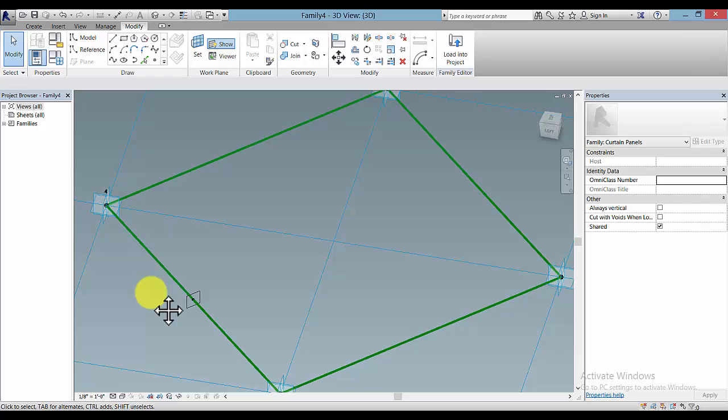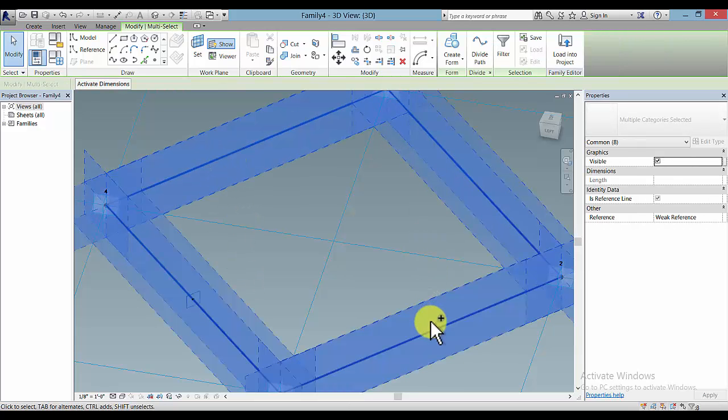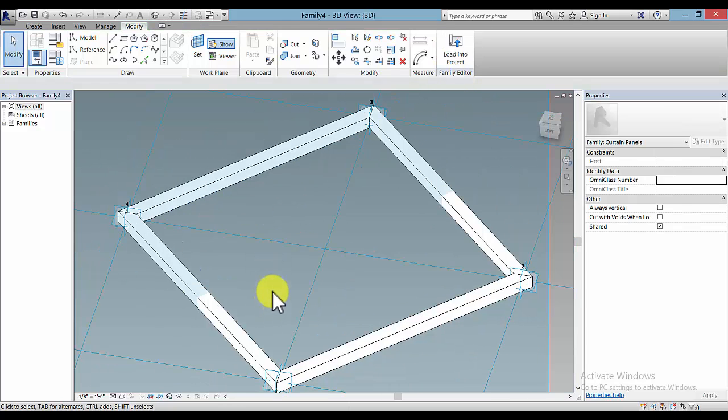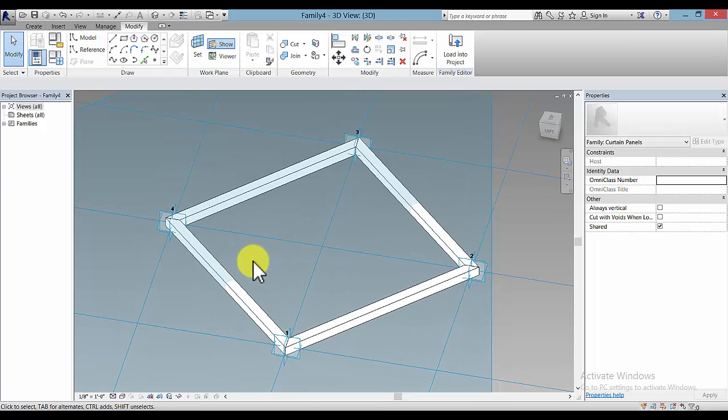the concept sweep. Here in creating your mass models, you don't have the tool called sweep like you do when you are creating a component in the Revit file. But if you select here this profile and hold your control key down and select reference planes, you can pick create form, solid form, and it will sweep along those reference planes and use that 8x8 profile to create that mass.